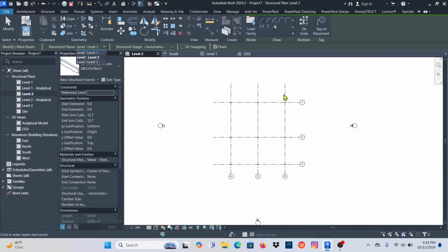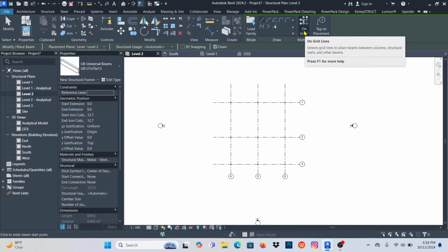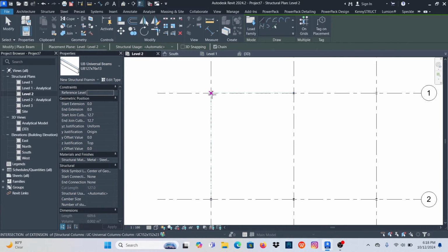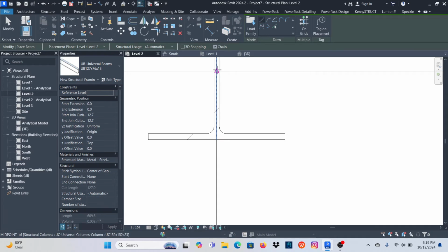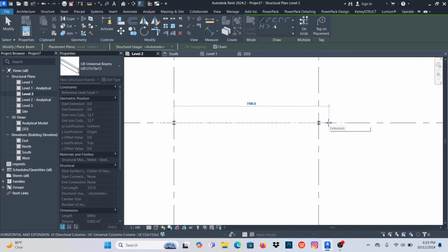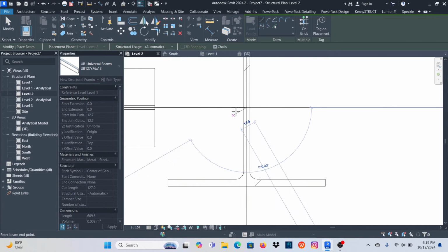But you can start creating your beams here, but the beams are physically being placed at level 3 if you pick level 3 or different level. So level 2 is fine. I'll leave the other options. Now you can place them on grids if you want, because it will place them between column to column. So I'll start with maybe by picking line, and I can zoom in here and have my beams just like that by picking that point and that point one by one to join them.